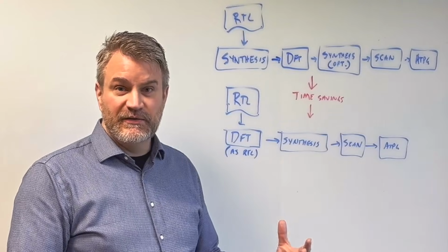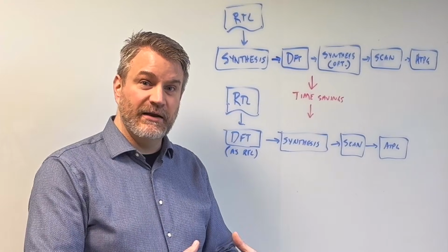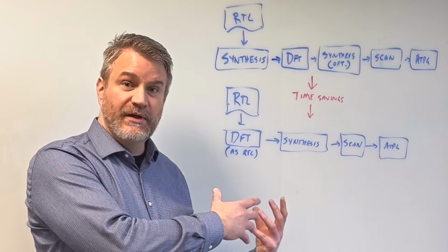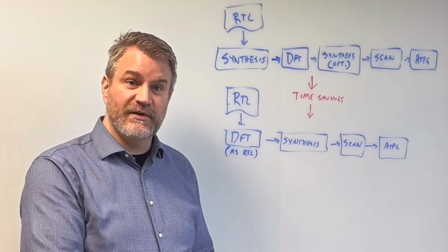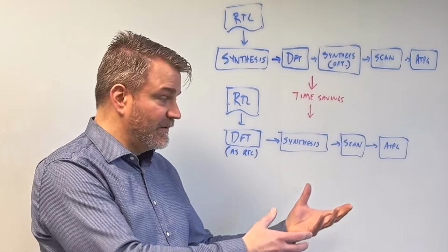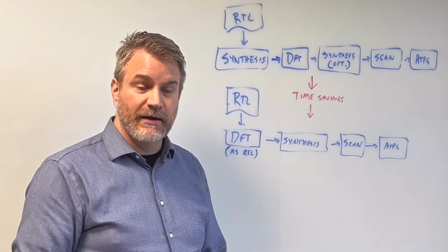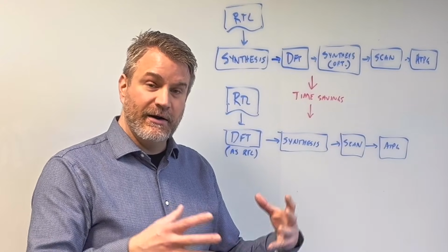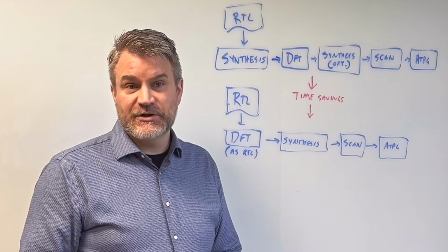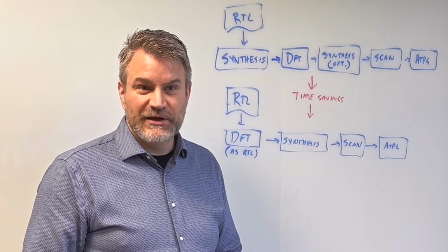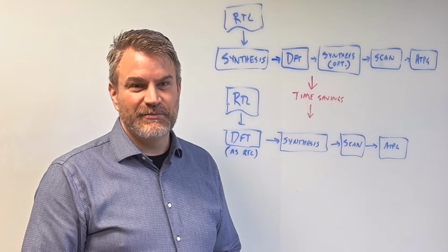We have the ability to then connect the entire design at RTL, and add test points to help with pattern count reduction and LBIST test coverage, all at RTL. And so these are the types of things that our customers are looking for so that they can pull their designs together at RTL and do all of that verification at RTL as well, because we all know RTL simulation runs a lot faster than gate level simulation.